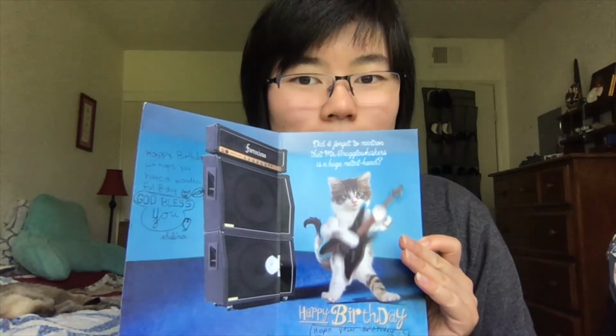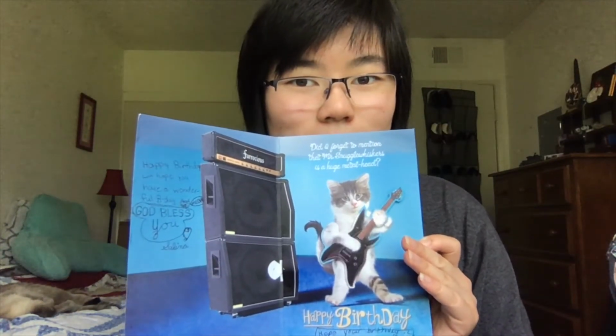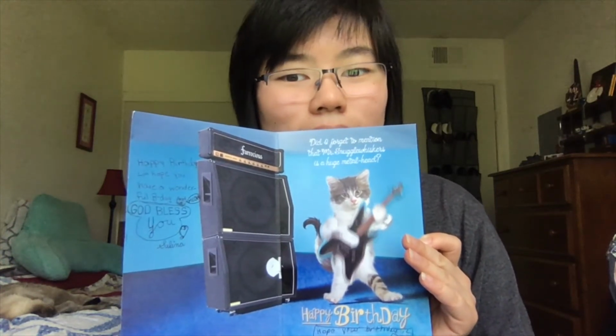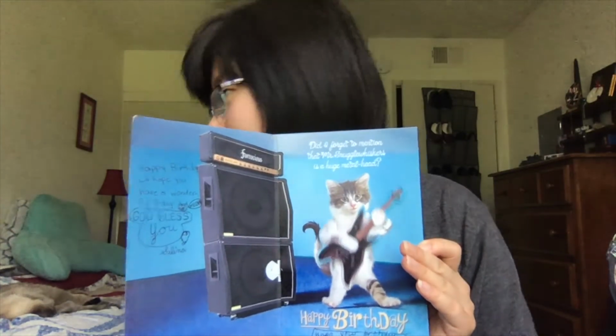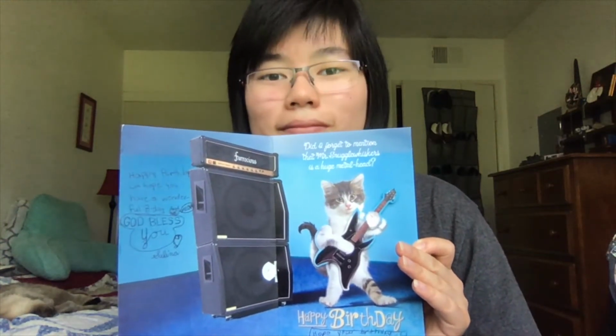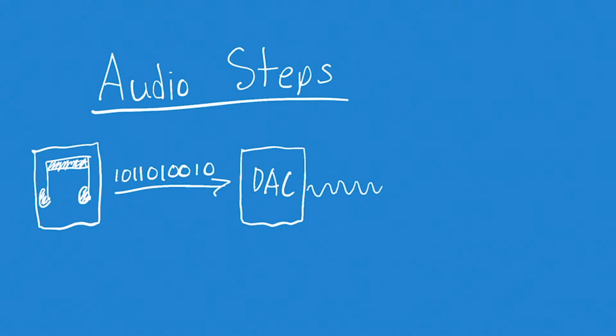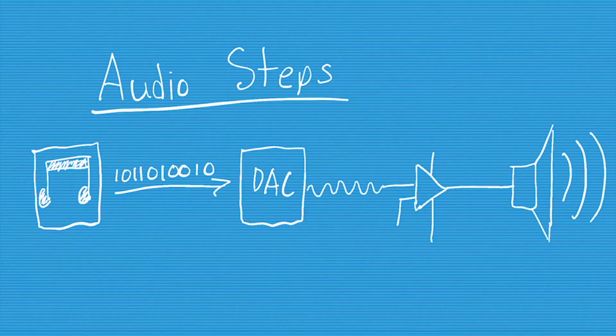Oh right, I needed a speaker. I stumbled across this. The next thing I needed to do was read data from a music file. Then I had to plug that data into a digital to analog converter, or DAC, to output an analog audio signal. The ESP32 had two built-in 8-bit DACs, however, they can't output enough current to drive the speaker, so before it's connected to the speaker, I needed to route it through an amplifier, which was...